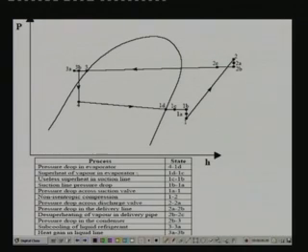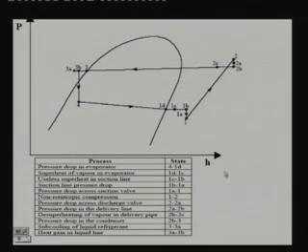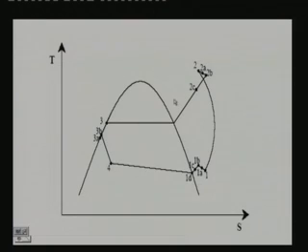You can see that because of all these pressure drops, heat transfer and all, the shape which was like a parallelogram has got twisted. Okay, initially without any pressure drop this should have been a horizontal line, but because of the pressure drop it has become inclined. Similarly in the condenser, because of the pressure drop you have an inclined line instead of a horizontal line. Like this there are various pressure drops and heat transfers listed here. Okay, and we shall see that the effect of all these pressure drops and heat transfers is ultimately to affect the performance of the system. Okay, the same thing is shown on the T-S diagram here.